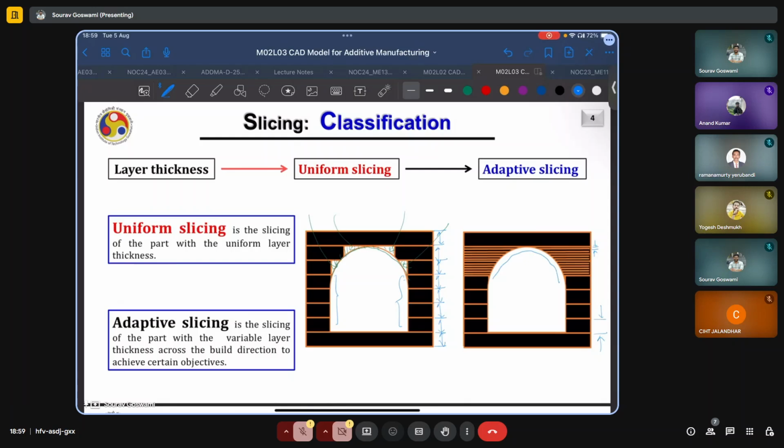Typically, the Z motion can be independently controlled, but you might still have a minimum layer thickness which you can deposit, and thus, irrespective of the height that you change, say by lifting your deposition head or by bringing your table down, the minimum height which you can deposit with your given feedstock and given process parameters for a material may still be larger and we might still miss out on accuracy.